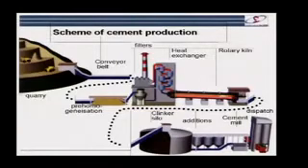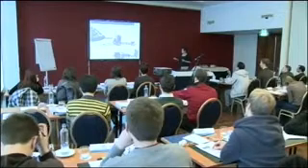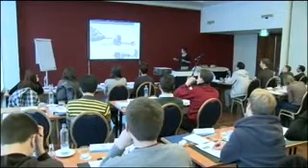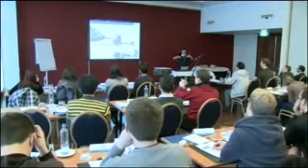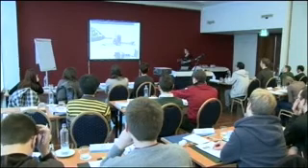And then typically now they have a kind of conveyor belt system to avoid pollution, etc., which conveys the limestone to the plant. And there they mix it with the clay and all other things. We're going to see that in a bit more detail. And then it gets fed into this rotary kiln. This is basically a long tube which rotates. Okay, so this is rotating.